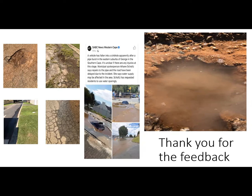I also had the privilege of going out and personally having a look at some areas in a dolomite area, where infrastructure is failing, and the effects on a tar road. As you can see in the pictures on the left-hand side, you can see the little doline that's been formed on the top left-hand side. On the top right-hand side, you can see the grass starts to grow, the cracks get bigger, and it completely breaks up the tar surfaces. And I've actually got a little video on the right-hand side, which I'd like to share with you.